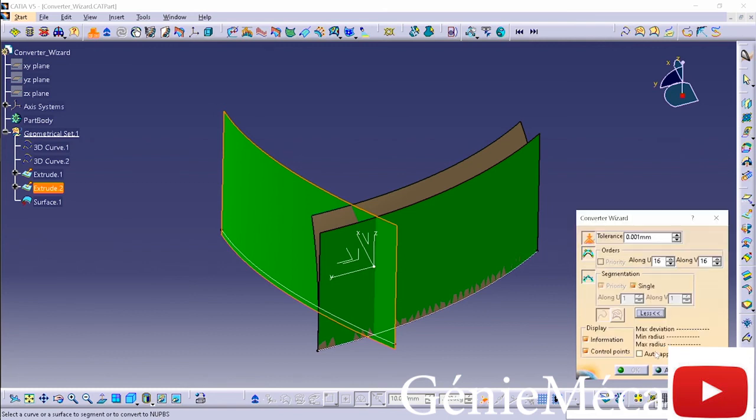We'll go into more and auto apply. You can see that there's no real deviation. This is a fairly simple shape. If I need to, I can reduce the complexity. I can increase the tolerance, something that may pull away from the original surface a little bit, but I get a much simpler surface. So if you're bringing something in from generative shape design and you need to manipulate it with control points, this allows you to do that and simplify that math as you're doing it.